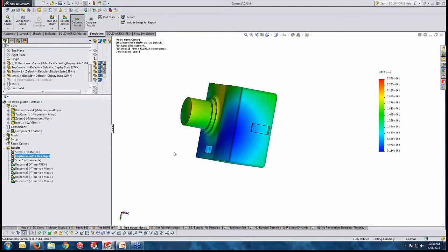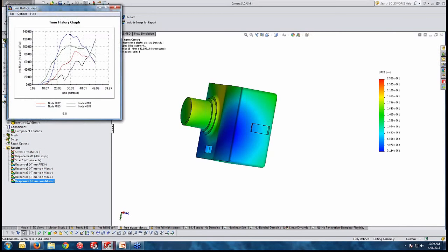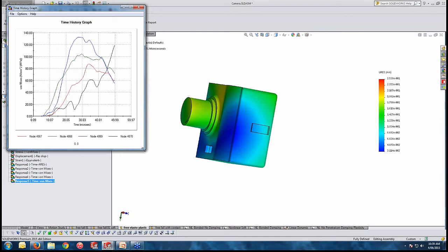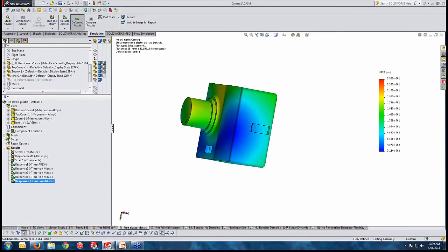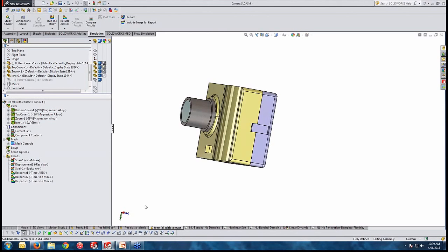Now we understood we are progressively reducing the top values of stress, either at a specific location we are looking at in a drop test, when we are considering more and more reality, like there is not a super stiff target floor, or if we have, let's say, plasticity in our material. Well, you can see that the maximum stress is reached somewhere around 30 microseconds, and after that it's dropping down to other values. As you can see, most of the nodes are simply dropping their stress values down to around 80 to 60 megapascal.